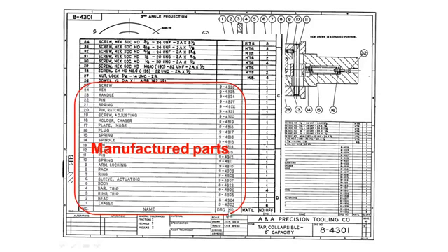And we've got here drawing numbers down here. So this is why when doing our detailed drawings, it's important to add a drawing number so we can reference our drawings later in these assembly drawings.